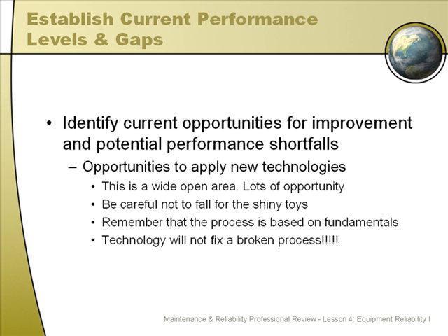Most operations that are looking for an improvement in performance tend to drift toward using technology or looking at doing things that are on the high end of our pyramid for the 5 pillars. In other words, they want to do it by using preventive, predictive maintenance, condition-based monitoring, and fancy doodads that go along with that. If you don't have a good process built at the foundation so that your equipment is maintained to be reliable and your process is designed to support that equipment, no matter how much technology you pour on top of it, you're never going to get there.